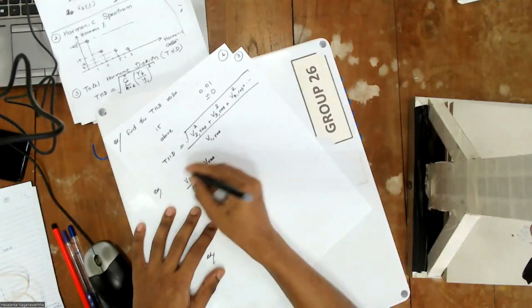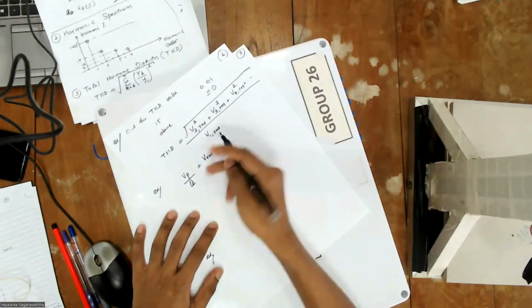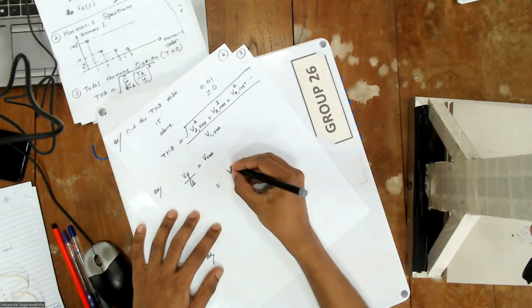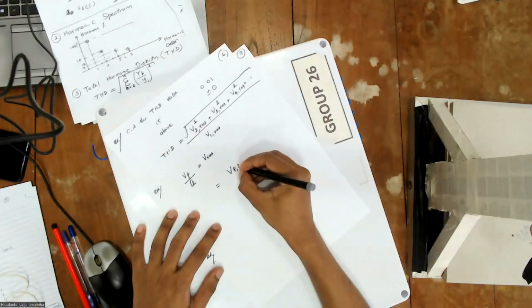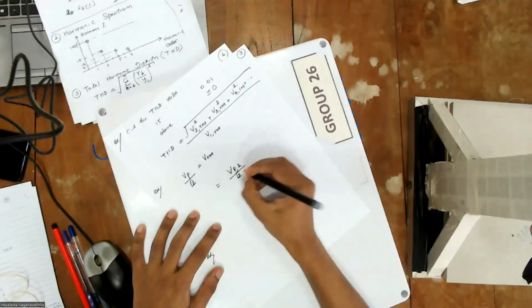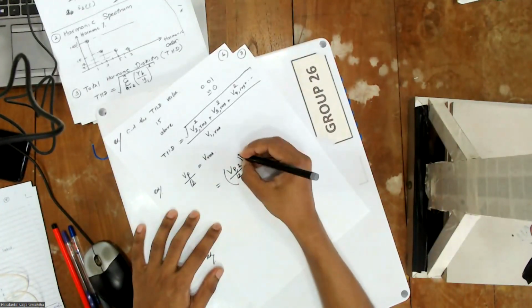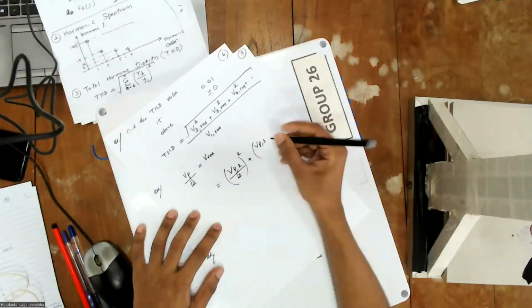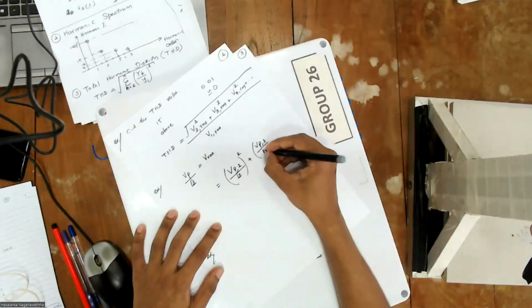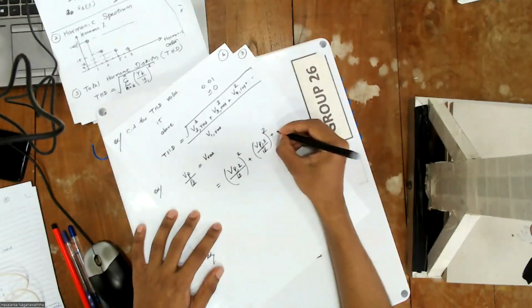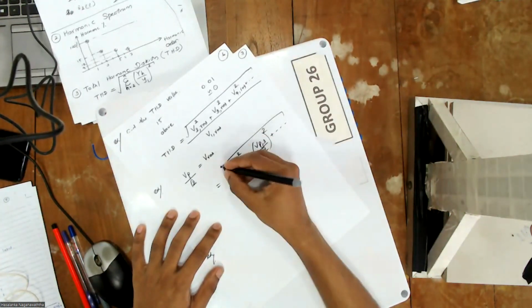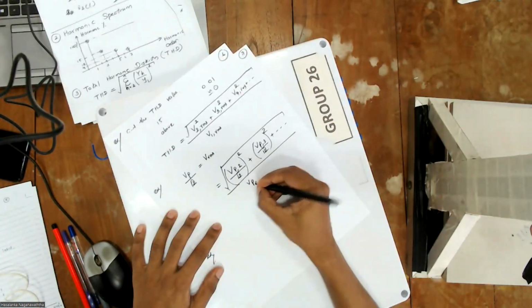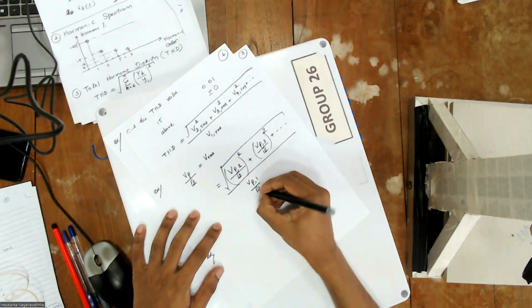If it is a sinusoidal signal, then you can substitute this here: V peak value of the second harmonic divided by root 2 and squared, then V peak value of the third harmonic divided by root 2 and squared, likewise up to n, take the square root, and divide it by the V peak value of the first harmonic over root 2.